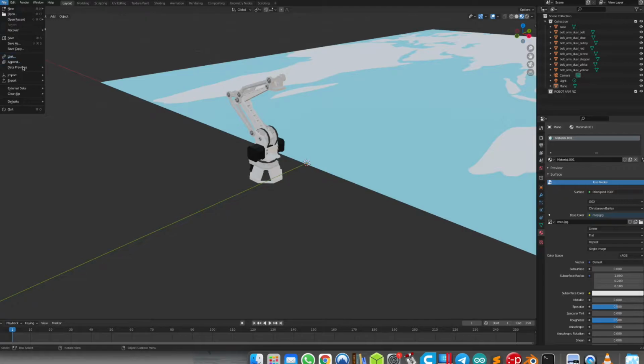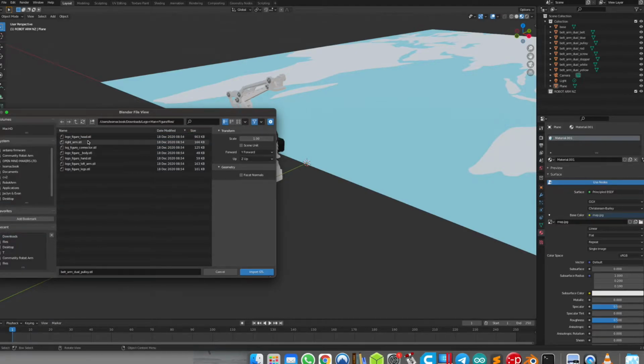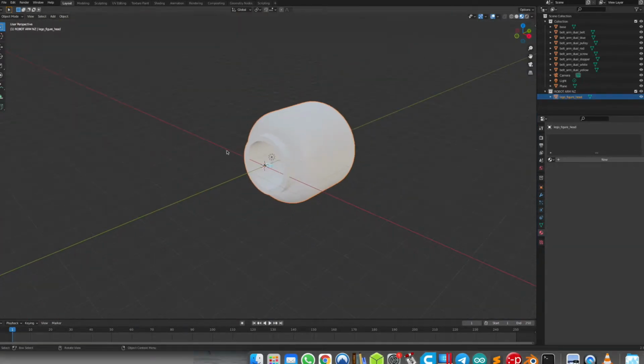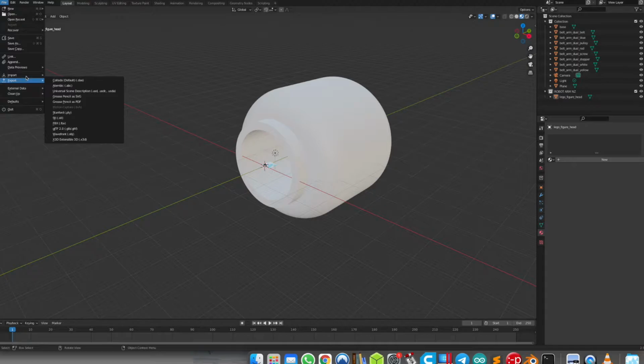Now it is time to import the STL files of the Lego Man and the helmet that we downloaded at the beginning of the video. Normally the STL files on Thingiverse or the ones we generate for our 3D printers are measured in millimeters, but the Blender workspace is measured in meters. Imported STL files will always be way bigger than the intended workspace. It is translating millimeter into meter values.